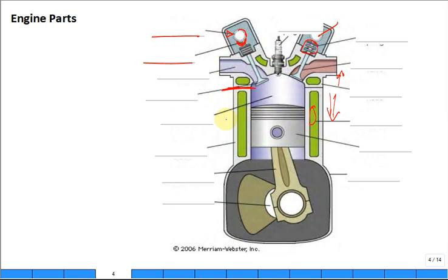Yeah. This is the piston, and it slides back and forth, and it's through this connecting rod. So that's the connecting rod. Down here is the crankshaft with a little bit of an offset between the center of the connecting rod and the center of the crankshaft. That offset determines how much stroke you get. This distance right here, you just say, hey, I think that's the distance that you're going to go. Two times the offset is the stroke. Two times the offset, crank offset. Oil pan down here, whatever.